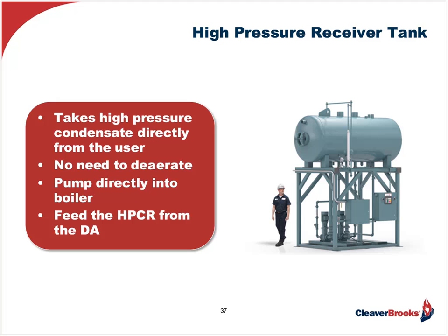Remember, for each 10-degree rise in feed water temperature, I'm going to say it again, we gain 1% in efficiency. And that says nothing about the water cost, the sewer charges, and the chemical charges that this venting incurs and that could be saved.